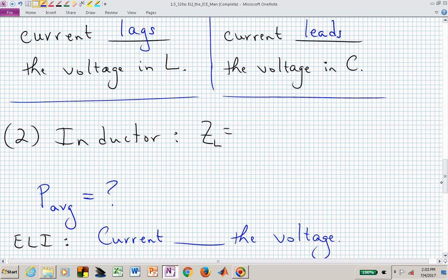So now if we look at the inductor, what is the impedance formula for an inductor? This is from an earlier class, and if you've taken it here, it would be ECE 220, where you looked at sinusoidal steady state behavior, and the impedance formula for an inductor was derived to be j omega L. And you can derive this if you simply look at a current waveform, a sinusoid, then this j omega L will pop out in front of the formula when you start differentiating that inductor's current.